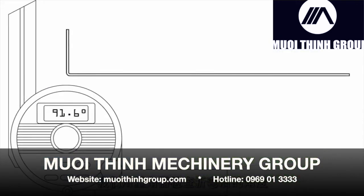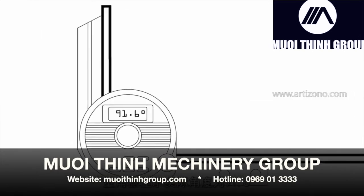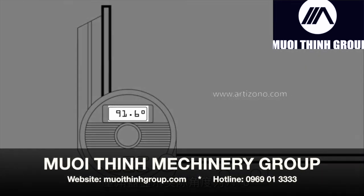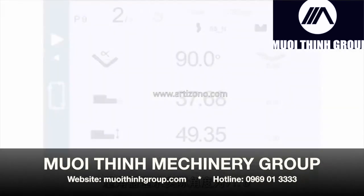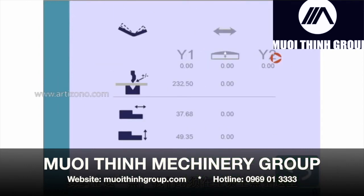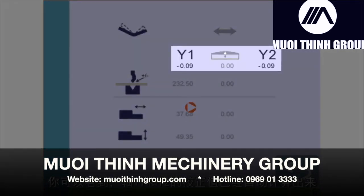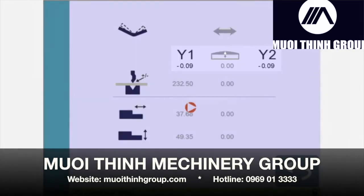Using a protractor, we'll check the angle of our bend. The measuring tool shows it is still a bit open. To be precise, it measured 91.6 degrees. To correct this, we must touch here on our main page. This opens the correction page, where we will simply enter our measured angle after touching here. As you can see, the values of axes Y1 and Y2 are automatically corrected accordingly.